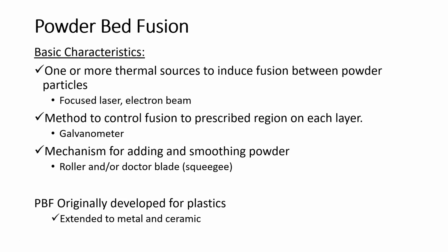And then we also need a mechanism for adding and smoothing the powder. And that's either going to be a roller or what's called a doctor blade. And the doctor blade is just a fancy word for a squeegee. Except in this case, you know, you're used to using a squeegee to remove water from your windshield. In this case, we don't want to remove the powder. We basically want to scrape it across the surface and distribute the powder evenly. Okay. And then, as I said, powder bed fusion was originally developed for plastics.